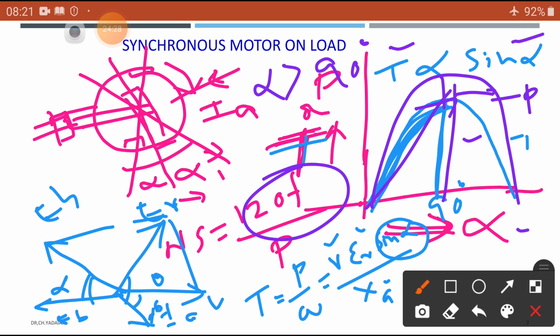However, you know that they serve the additional purpose of making the synchronous motor self-starting. Here dampers serve two purposes: one is preventing oscillations, that is hunting, and at the same time, they work as an induction motor during starting of our synchronous motor.